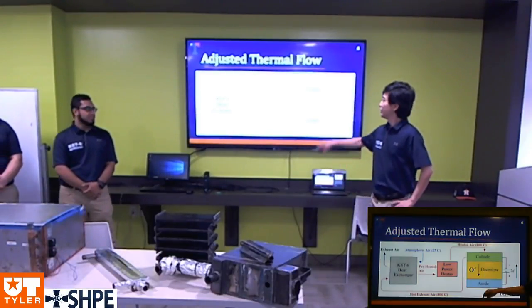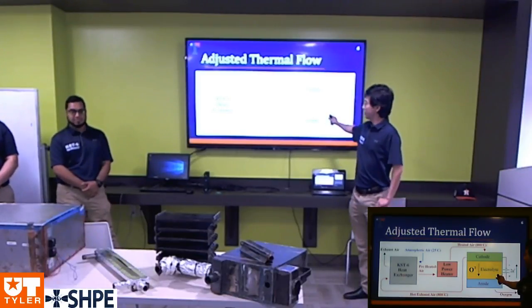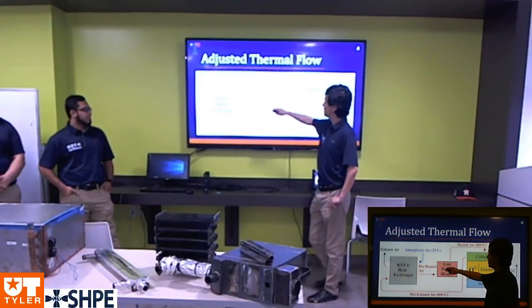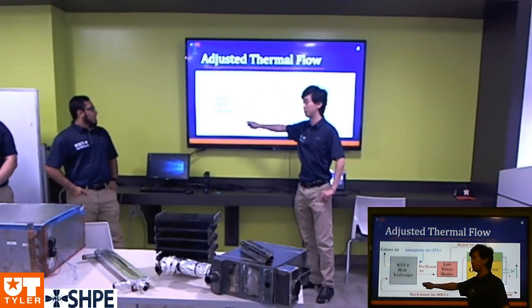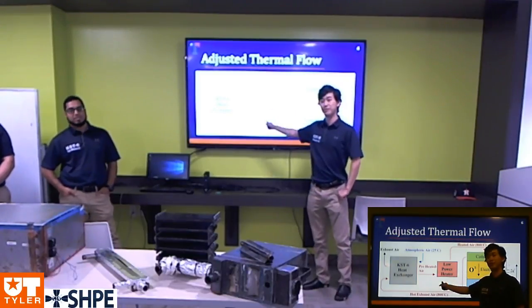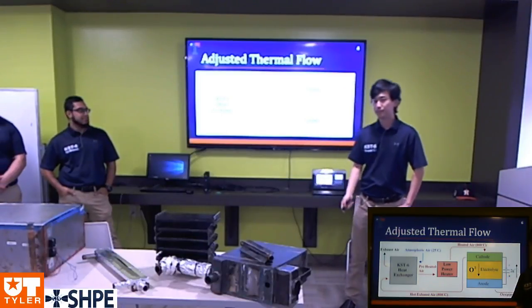As we move on, this is how our heat exchanger goes into the thermal system. As you can see, the hot 800 degrees exhaust comes into the heat exchanger, which then preheats the atmospheric air to a higher temperature, which we can then feed into the heater. This heater now takes less power than the previous one, and we can save power and make it safer.